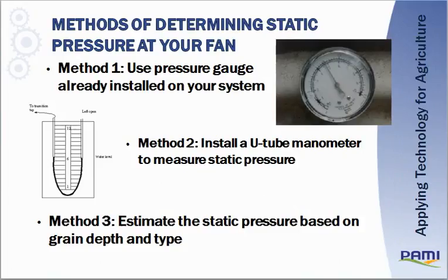Okay, so static pressure is important. That's really what dictates the amount of airflow rate you get out of your fan. How do you measure it, or how do you determine it? Well, I'm going to talk about 3 different methods. The first 2 are actually direct measurements. The third one is an estimation method that is really better suited for sizing the fan before you actually purchase a fan. But method 1 and method 2 involve actually measuring the static pressure your fan is pushing against.